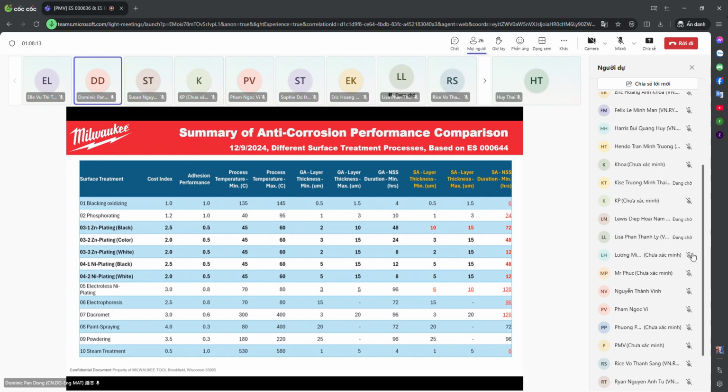So these treatments are only designed for anti-corrosion during the transportation of the raw parts to the assembly line. They cannot provide any guaranteed anti-corrosion performance in service. I guess you would have seen end-user complaints of corrosion or rust on parts after black oxidizing. That's commonly seen.